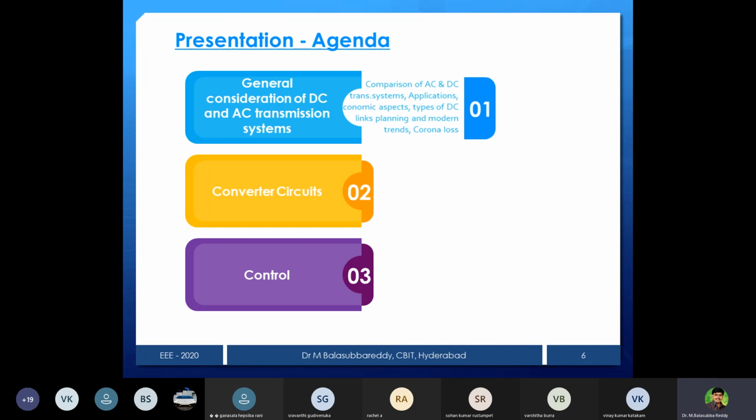In a rectifier, what type of commutation will be used? Which commutation is used in a rectifier? Natural or forced commutation? Natural commutation. Yeah, so in a rectifier, natural commutation. Why? Because the input is an AC supply that is going to naturally go to zero. Maybe it depends on your load. It may be pi or beta or pi plus alpha, whatever may be the scenario.